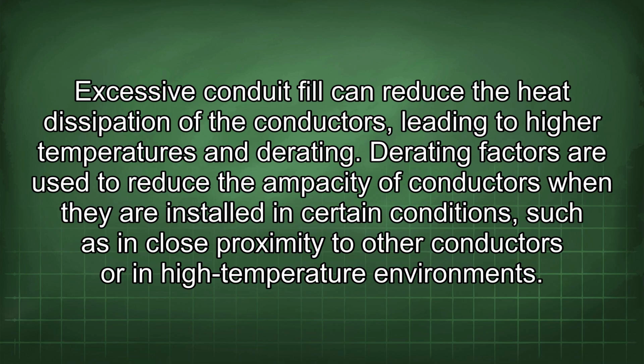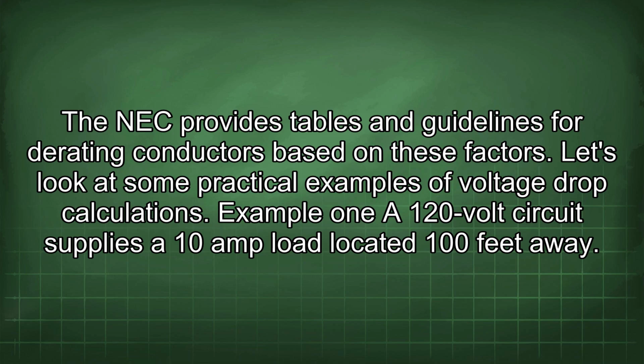Derating factors are used to reduce the ampacity of conductors when they are installed in certain conditions, such as in close proximity to other conductors or in high-temperature environments. The NEC provides tables and guidelines for derating conductors based on these factors.